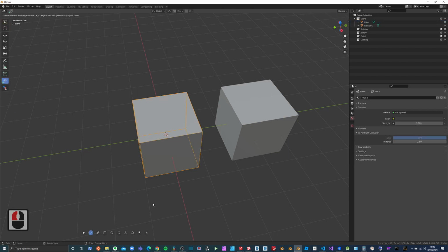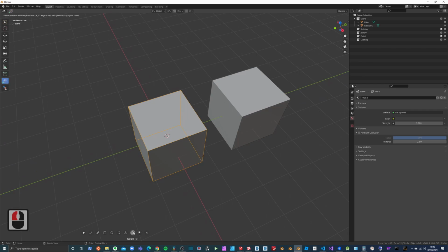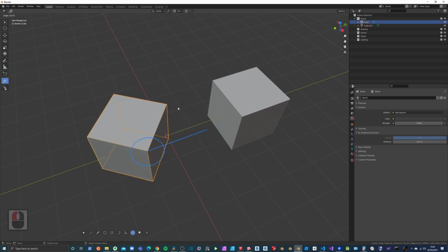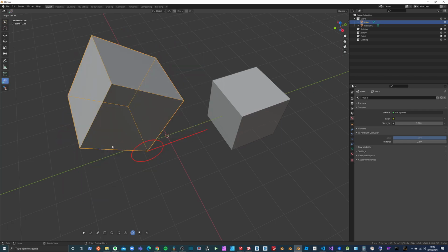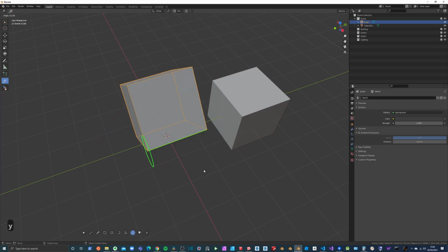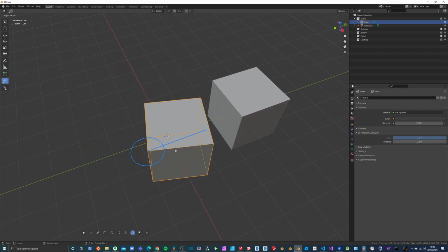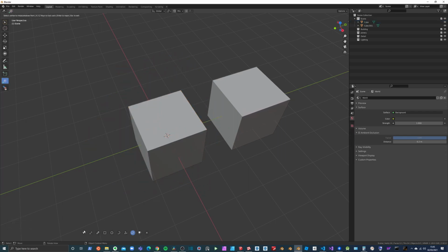Whereas now, with construction lines, if my object's already selected here, if I hit rotate, my first click is going to be that pivot point. It's automatically set to that point now, and then I simply choose the plane on which I want to rotate. I'll click my second point, and then I'm free to rotate, and I can use the x-axis, y-axis, or head back to the z-axis.